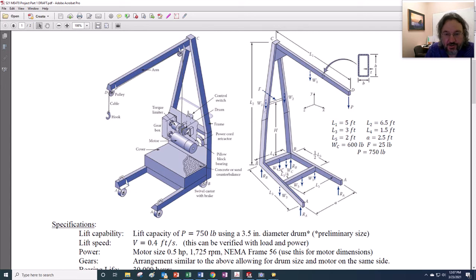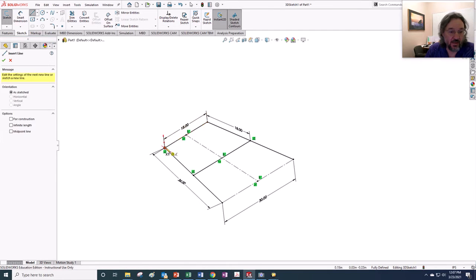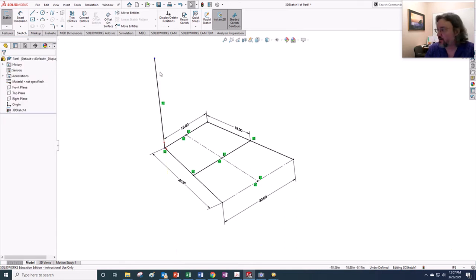In Weldments, this thing can get all kinds of skewed, and you're going to get all screwy. So instead of sending you down that rabbit hole, I'm not going to do that. Okay, I'm going to make it straight up, so it's going to be in the Y direction right there, and I'm going to push it right around that spot.